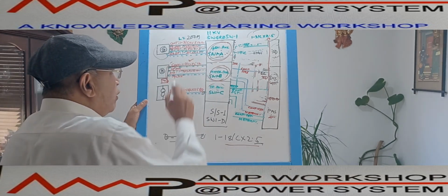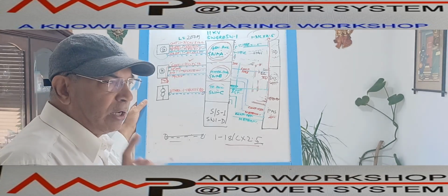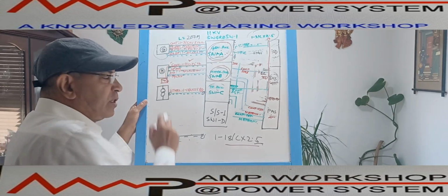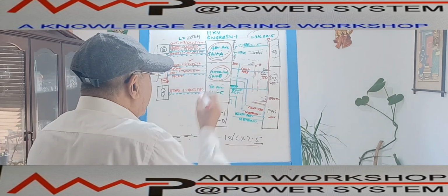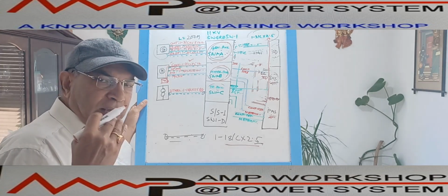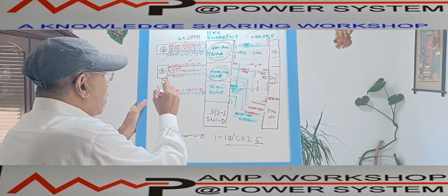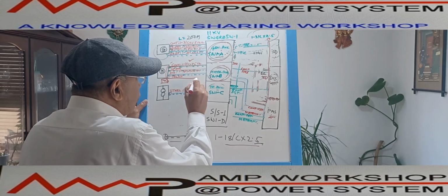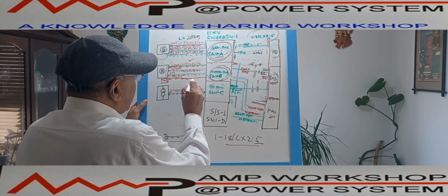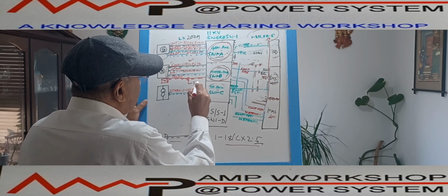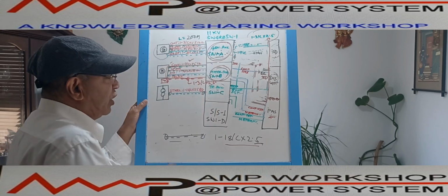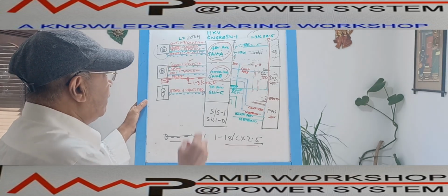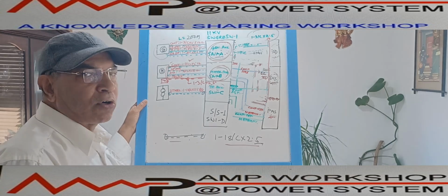For that purpose we use one 7-core cable, which will give a command from the motor skid for the breaker on and off, or the feeder on and off. In addition to this, for the emergency push button, from the motor skid there will be another cable connected over here, which is 1 3-core into 2.5 square millimeter, same as the generator. That is for the emergency push button. That is also connected to the motor switchgear panel.